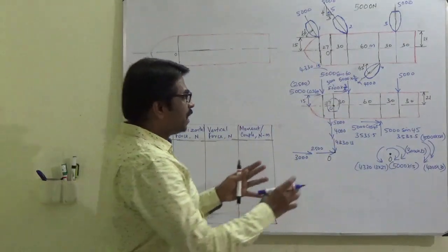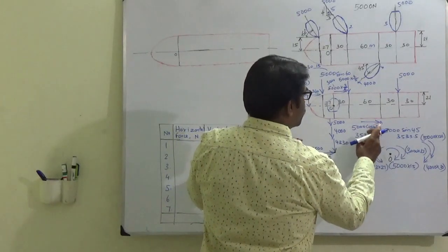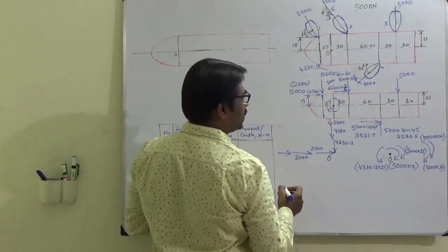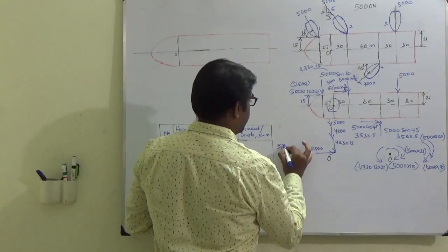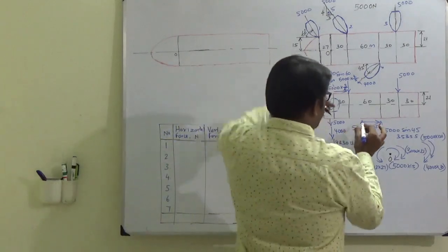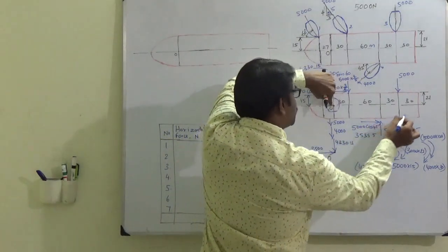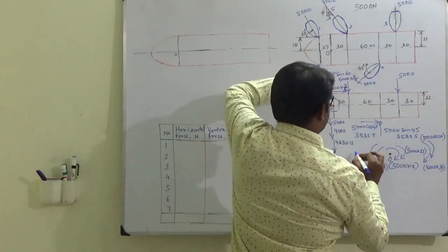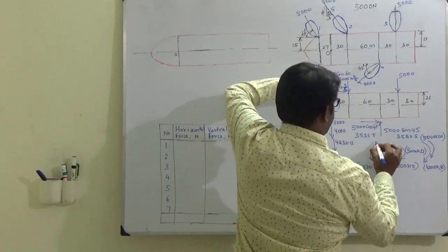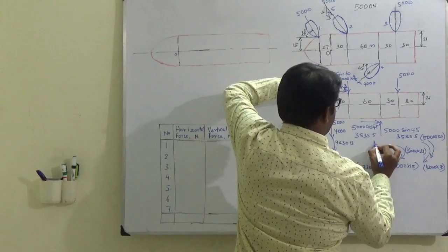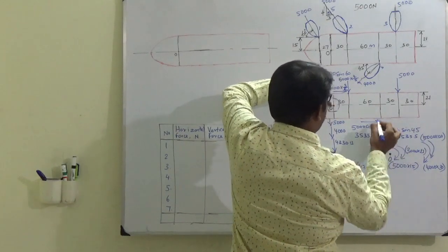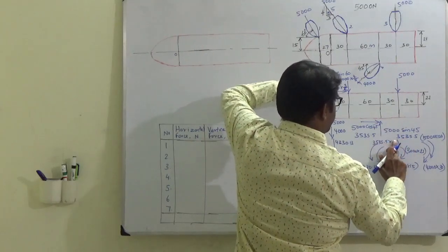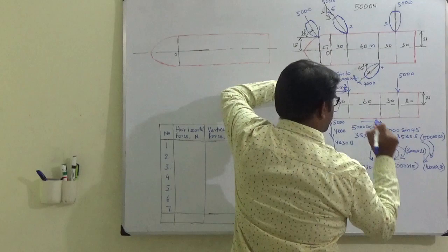Right? Now we have two more forces. This is towards right. Okay, I am placing it here. 3535.5, and it will produce, about this point, an anti-clockwise moment. So that is, the value is 3535.5 into 21. The horizontal force.